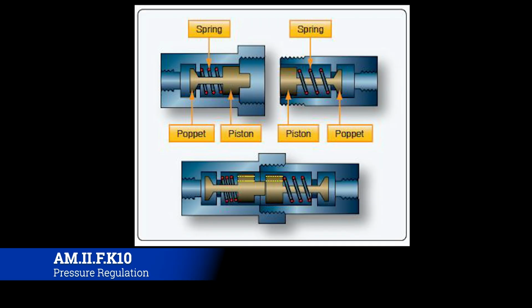Okay, so let's talk about quick disconnects. These are actually two valves that meet up together. Now, why would you need a quick disconnect? Well, there's a couple of scenarios where you may need to disconnect the hydraulic system. Say you're doing some sort of maintenance. What you don't want to have to do is crank the engine or turn the battery power on to run hydraulic pumps to pressurize the system. So they have a cart that they'll roll up next to the aircraft and connect up there, and that supplies hydraulic power directly to the aircraft.